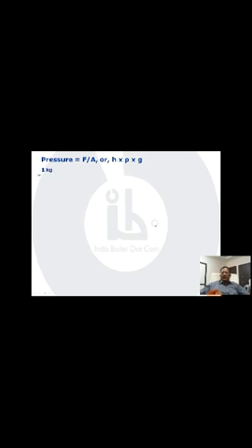Okay, let's take a look at the different pressure units, conversion from MKS to SI. Now, whenever we find the MKS system, I'll tell you one thing. If you see kg force and you want to convert it into Newton, you just multiply it by 9.81. It gets converted to Newton, right? So we convert this kg into Newton, centimeter square into meter square. So 9.81 on the numerator, 10 raised to minus 4 on the denominator. This 10 raised to minus 4 goes up, it becomes 10 raised to 4. So 9.81 times 10 raised to 4 Newton per meter square.